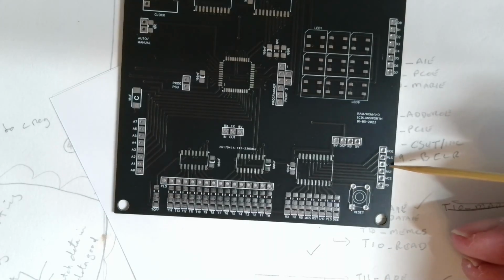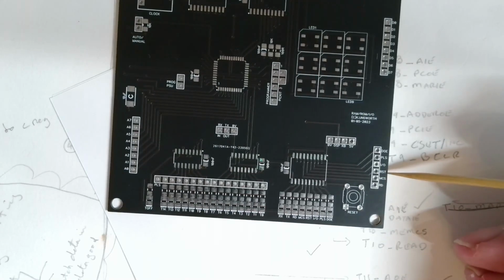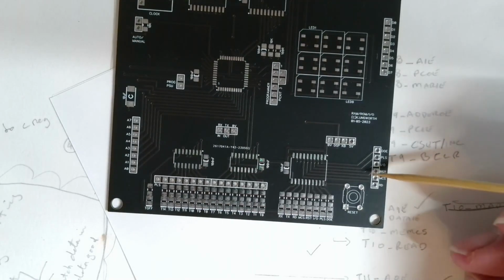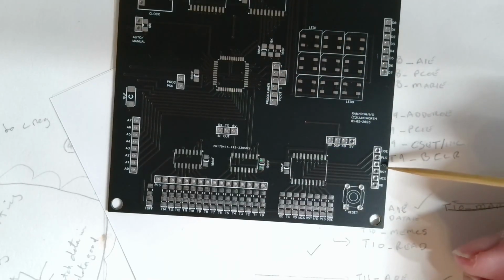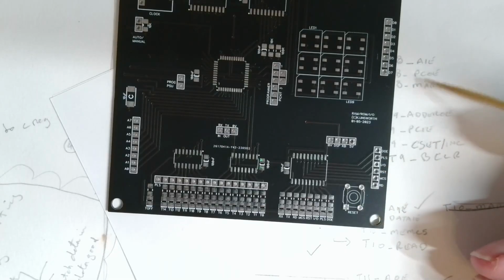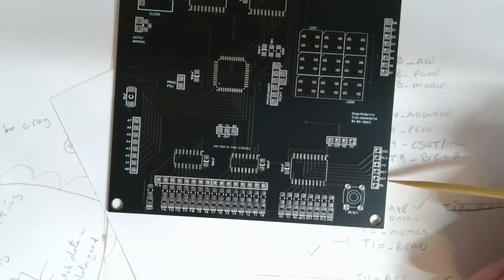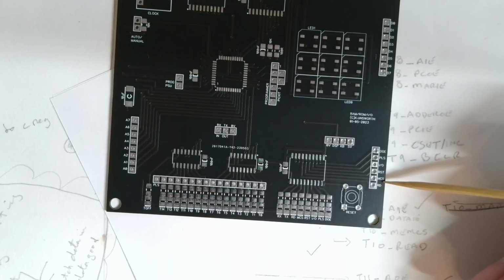And we've got the I/O to say whether it's an I/O read or write rather than a memory. Then there's the reset signal, which comes out of here for a short while, but is normally fed back in to actually reset the processor there as well, if you assert that with the reset button here. But this reset goes out and resets all the registers. Then you've got the memory chip select, which is the opposite of the I/O. That's to let you know you're accessing memory.